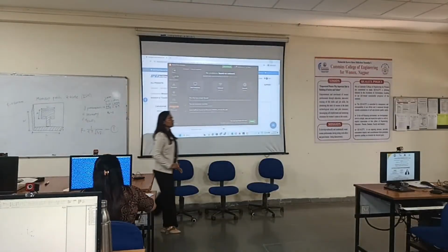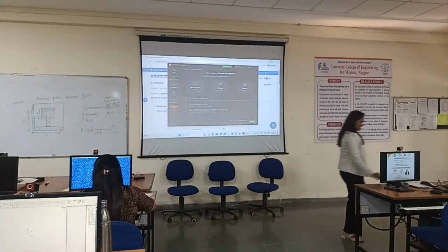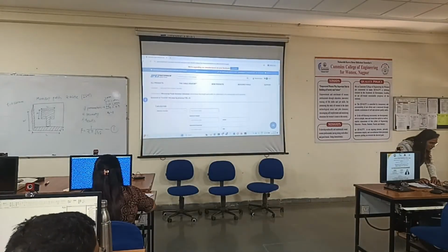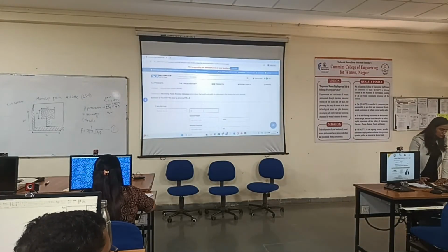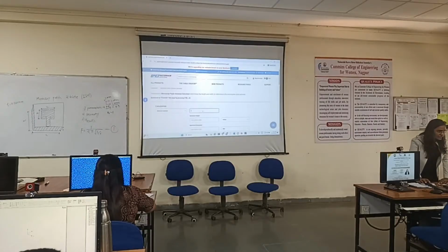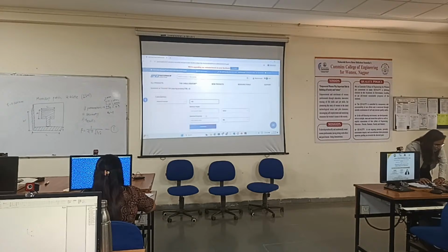So now I'm not going into calculation. I can directly use here a microstrip calculator, where I have to give the input as a dielectric constant. You can use it on your laptop. Just type microstrip patch antenna calculator and dielectric constant 4.3. Height of the substrate I'm going to consider here 1.6 mm.